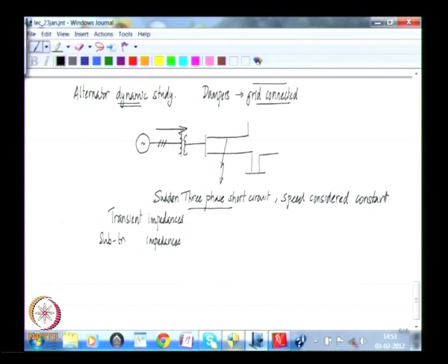So far in the machine models that we have derived, we have not defined any of these terms. All that we had for an alternator, for example, if it is a salient pole machine, we talk about the direct axis impedance and then the q axis impedance, whereas now in order to quantify the behavior of the alternator when connected to the grid and subject to disturbance, you will have to come across new terms, which one designates as transient or subtransient impedances.